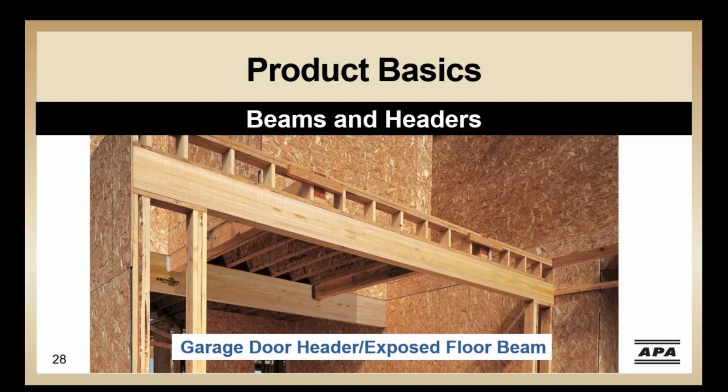Also note the beams used for garage door headers or even APA's narrow wall bracing method. In a wall, a 2-ply LVL at 3.5 inches wide fits nicely in a 2x4 wall, and glulam beams available in 5.5-inch widths will fit nicely within a 2x6 wall. By selecting a beam that matches the depth of the wall, we can minimize furring that would otherwise be required for the connections on both sides with the APA narrow wall bracing method, with a panel connection on the front and a strap on the back of the beam.